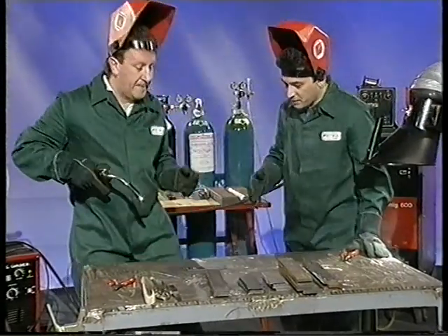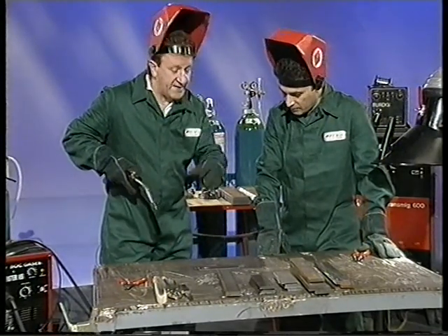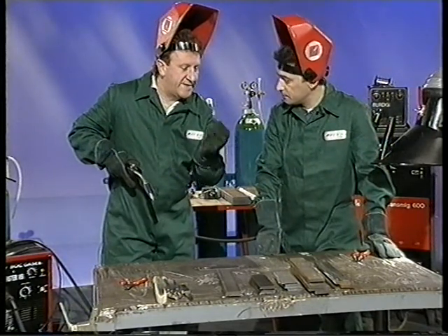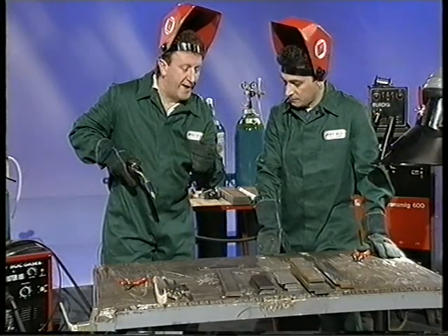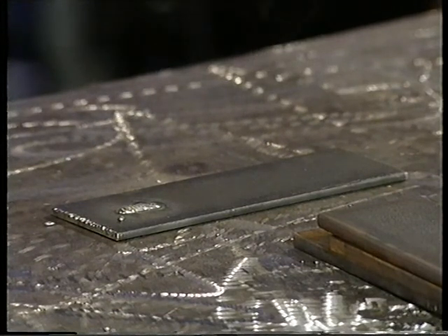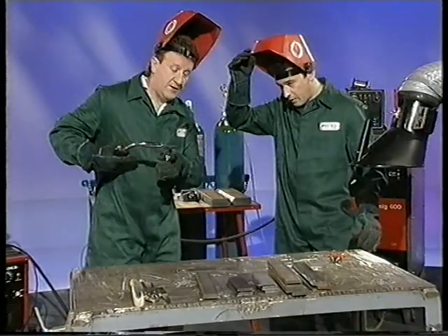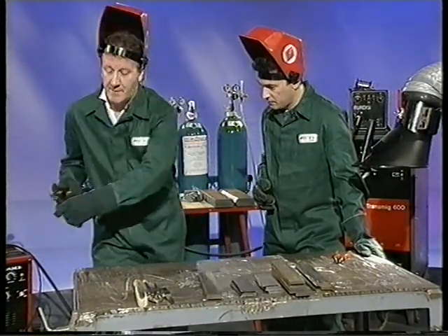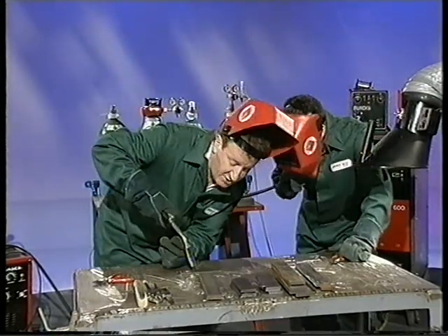Okay, sounded a little odd to me there. Yes, it is. That's got too much voltage or not enough wire for this particular dip welding condition that we're trying to set. You can see that there was a very long arc length, and rather than short-circuiting, the molten material was forming a ball on the end of the wire. So if you would try turning the wire feed speed up to 8 meters a minute from the 4 meters that it was. Okay. You can see the ball on the end of the wire there. It's always advisable to snip the end of the wire before you start to make sure that you have a good start. Now let's try again, mind your eyes.